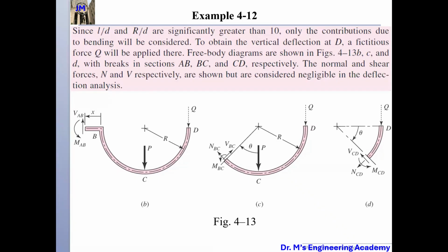And the length equals R multiplied by sin theta plus another R. So the arm of Q is R plus R sin theta. So this is MBC, and then we take a look at dMBC over dQ. Once again, the P term has nothing to do with Q, and we only have this one, which equals R plus R sin theta.